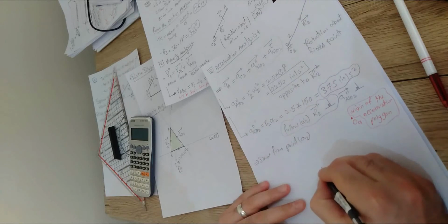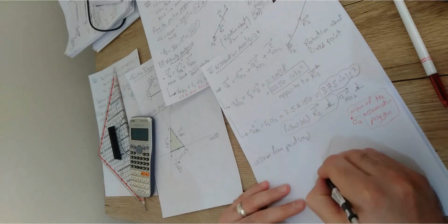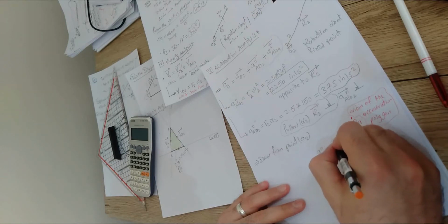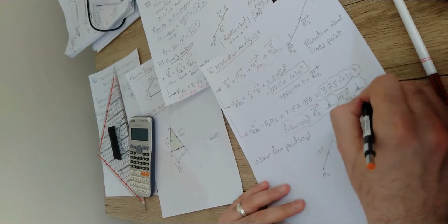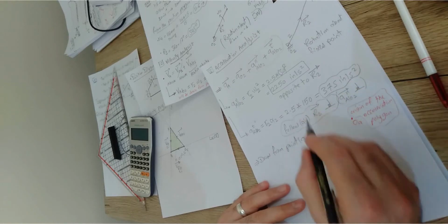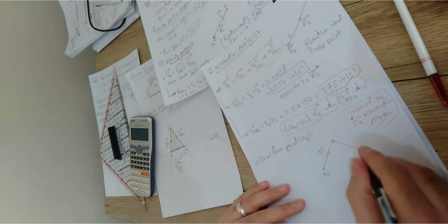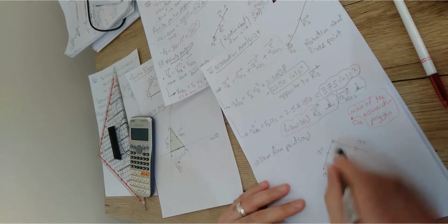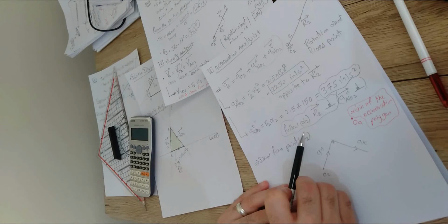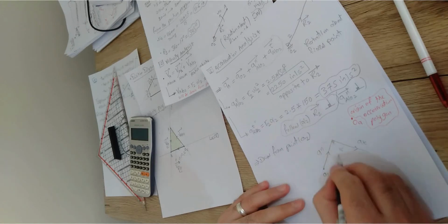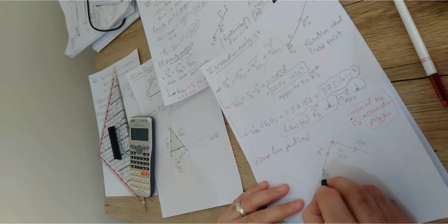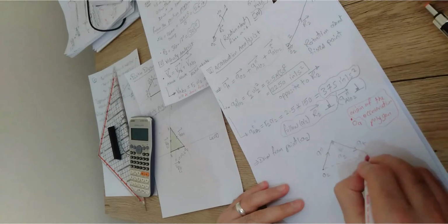Then from O2, let's say that this is the direction of A normal, you're going to draw A normal. Then you're going to draw the A tangential perpendicular to it, as we said that generally it should be perpendicular to the A normal, which is along the R2. You go perpendicular to the A normal to draw the A tangential in the same direction as alpha 2. The perpendicular to A normal would be either this direction or this direction. Assume that the direction of alpha 2 is this direction, so I'm going to go down. This is going to give us the A tangential. If we connect these two points together, this is the end point.